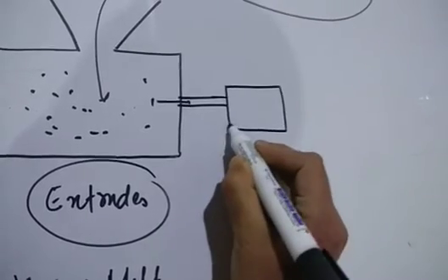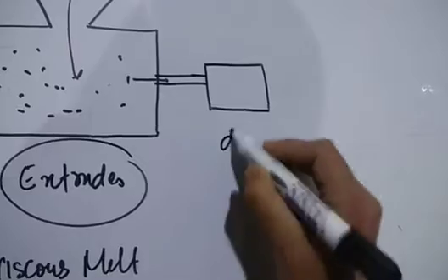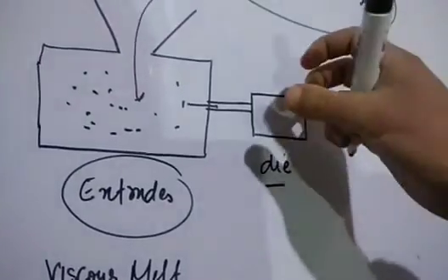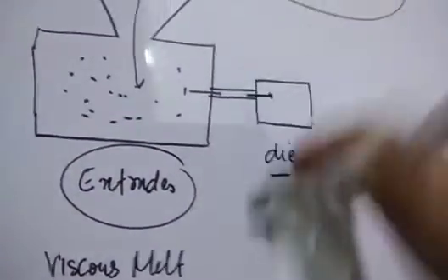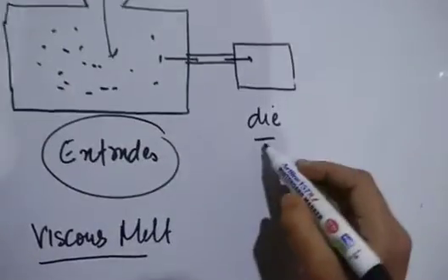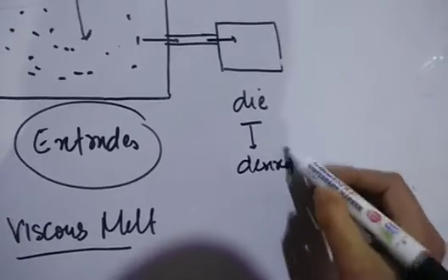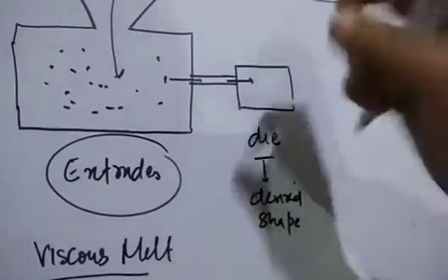Second component of this extruder method or technology is the die. So what this die does, die में different shapes automatic होती है. तो polymer जब वहां से pass हो जाता है, उस polymer की वही shape होती है जो die में shape होती है. So die gives polymer a desired shape. एक shape इसकी आ जाती है article की automatic यहाँ पे die में. तो die जिस तरह से हो ऐसी ही shape बन जाती है.